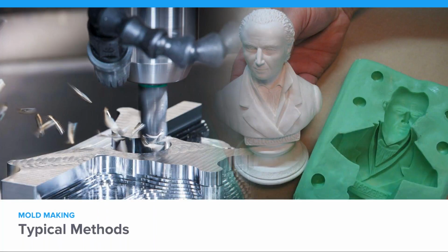So a lot of people turn to silicone casting, which you can see on the right. Silicone casting is very cheap. It's great for one-off projects. I'll go over how many pulls you can get out of them in a second. They're very forgiving. Even if you have undercuts where one half of the part can't be pulled out of the mold, you can flex a silicone mold so that you can wrench the part out. The downside is it requires a lot of upfront time investment to make the mold, and you do need a master part, whether that's 3D printed or hand sculpted, before you get started.